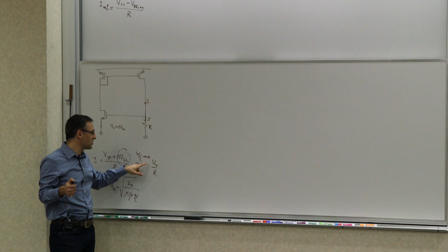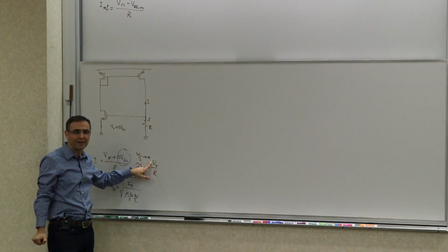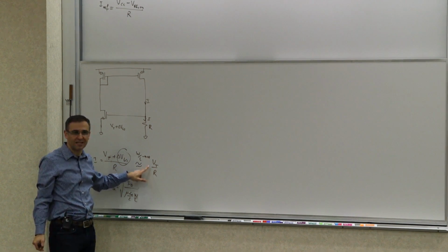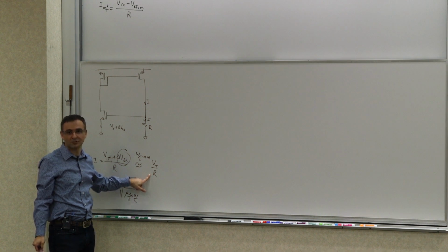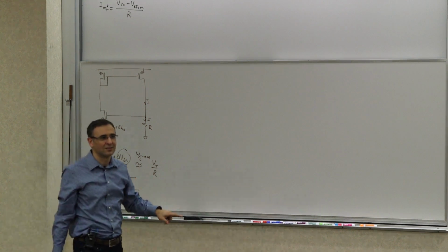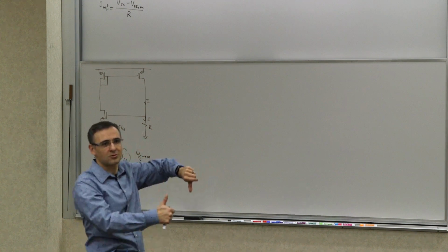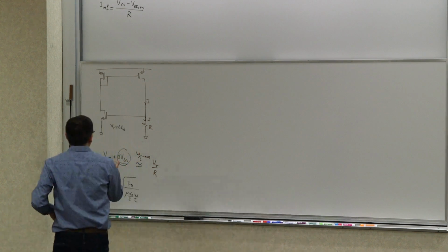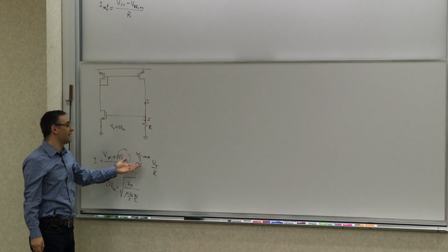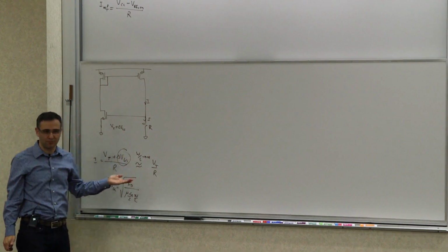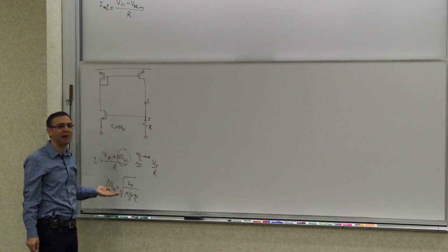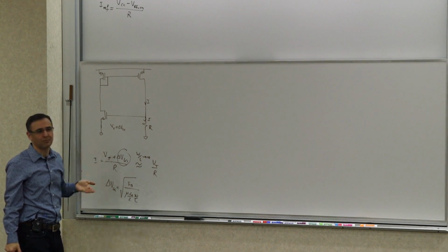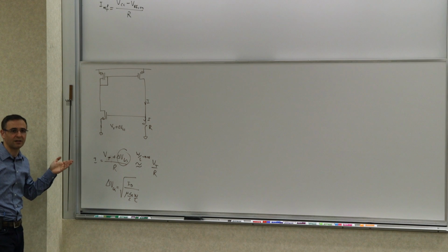How about temperature? Well, I just told you that VT has a negative temperature coefficient, and a regular resistor, let's say, will have a positive temperature coefficient. So is that a good thing? A ratio of a negative to a positive is not good, because the numerator becomes smaller and the denominator becomes larger with temperature. So that ratio doesn't stay constant. So it's good from a supply perspective, but it's not very good from the process and temperature perspective. They call them PVT: process variations, voltage variations, and temperature variations.